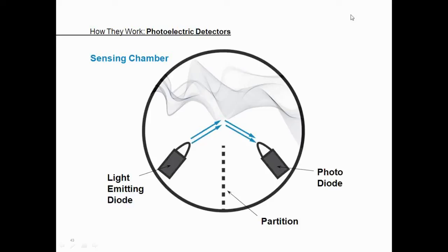The type of smoke created by a fire depends on what is in the space and what will burn. Most items that would burn inside of a building would create a gray smoke, not black smoke. So for this reason, NFPA recommends photoelectric type detectors for duct applications due to the high likelihood that white or gray smoke will be present.